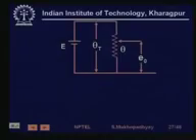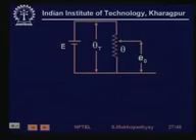For example, typically, a potentiometer. I was talking about a resistance, right? A potentiometer is nothing but a resistance. Potentiometers typically measure position, so the potentiometer will be connected to this variable point. As the variable point moves, the voltage that you will get will be directly proportional to the position, right?